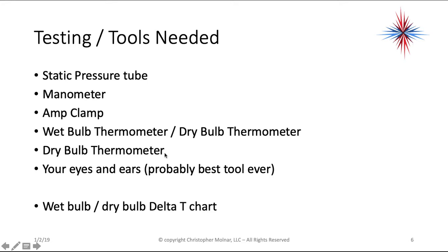I always also have a second dry bulb thermometer because I like taking my temperature readings all at the same time. You need to have your eyes and ears. I'm going to tell you right now, that is probably the best tool ever because you can hear airflow problems once you start getting used to it.